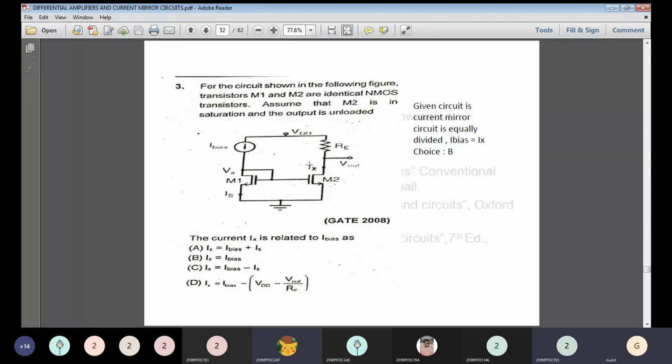In the current mirror circuit, in the theoretical section, we discussed that Ix, that is I output. Here it's mentioned as the output current. Ix current is the output current. This Ix current is equal to I reference; here the I bias is given as the I reference current. Only the notations are different here. When this Ix becomes equal to I reference, Ix is nothing but the output collector current and I reference is the reference current. So that is the concept of current mirror, right?